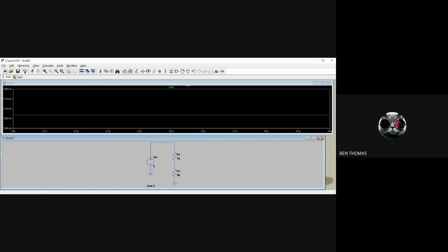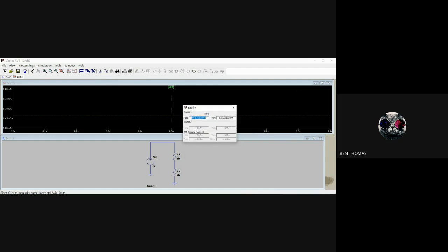And if you want to obtain the exact value, you can see the heading IR1, the heading in green color. If you click on that, you will get a pop-up like this, and this has the exact value. The horizontal is 499.71182 millisecond, and the current at that point would be 1.6667 milliampere. You can get it accurately.